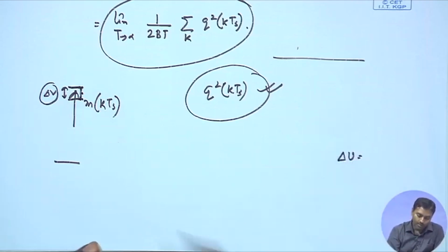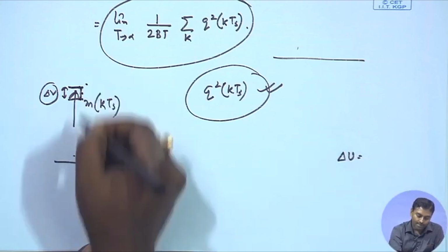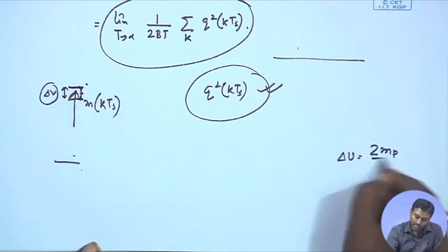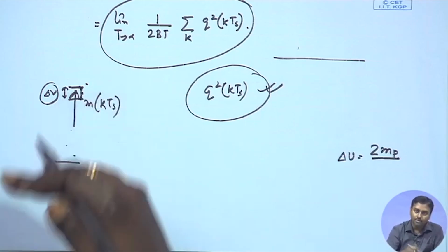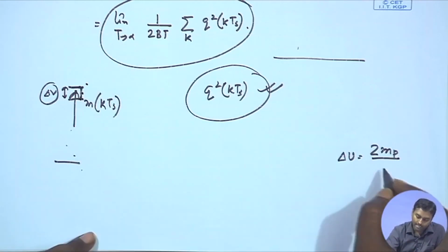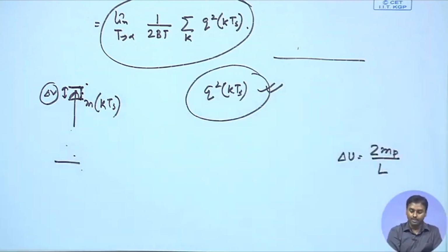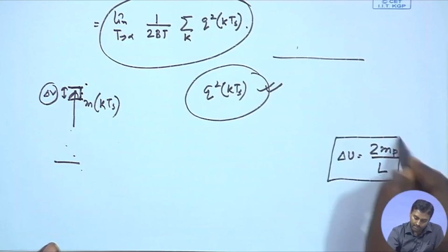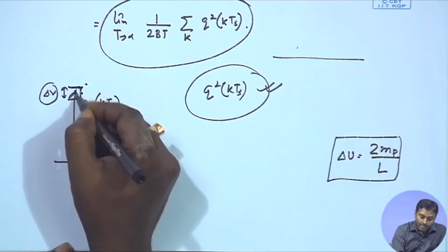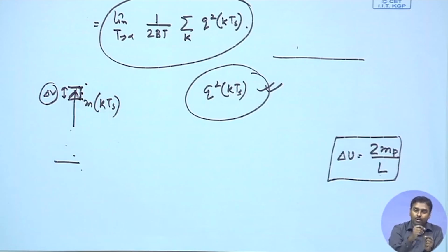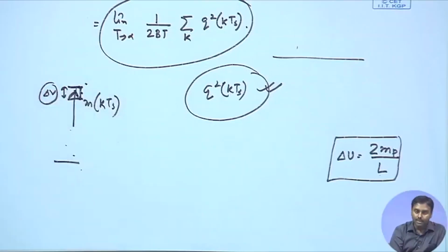Del v is equal to, the overall range is from plus mp to minus mp. So, that is 2 mp divided by as many number of levels I will be creating. So, let us say that is L. For our example, L was 256. So, 2 mp divided by L is my del v, and what happens? Within this, we are now assuming that the samples are uniformly distributed, that is what our assumption is. So, if the samples are uniformly distributed, what is the corresponding error? Because any sample we get will be represented by the middle value. Okay. So, the corresponding deviation will be from the middle value, whatever it is.